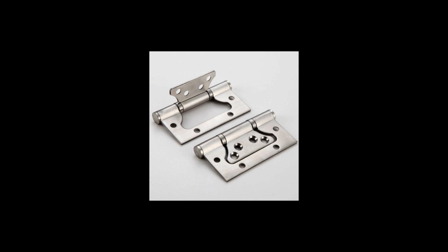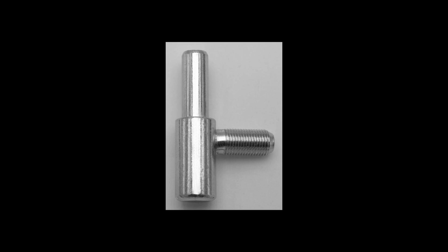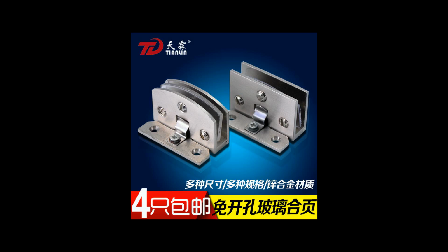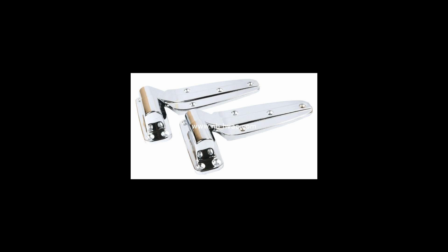Large structures. Hinges appear in large structures such as elevated freeway and railroad viaducts. These are included to reduce or eliminate the transfer of bending stresses between structural components, typically in an effort to reduce sensitivity to earthquakes. The primary reason for using a hinge, rather than a simpler device such as a slide, is to prevent the separation of adjacent components. When no bending stresses are transmitted across the hinge, it is called a zero-moment hinge.